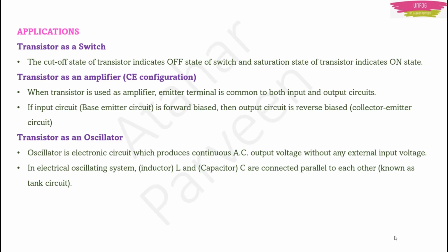Now along with amplification, these transistors have two more very good applications. First is that transistor can be used as a switch. Here in the transistor, there is the base, right? In that base, if you give current, the transistor will act as an on switch. If you stop giving current at the base, then the transistor will act as an off switch. Okay, so you can use transistor as a switch.